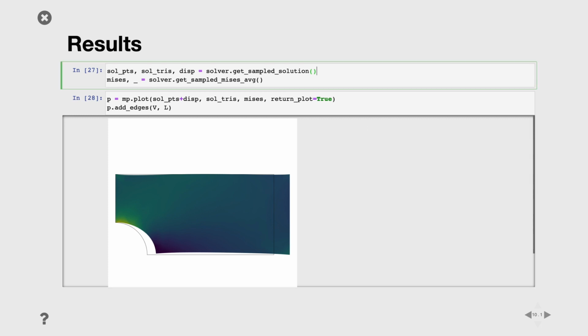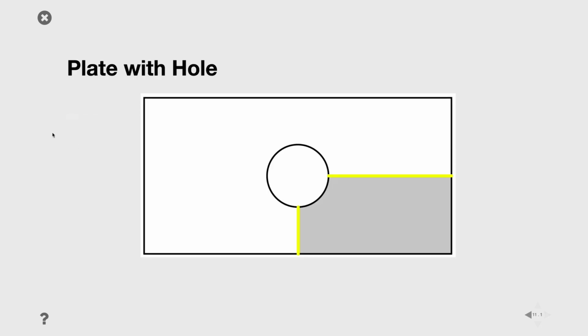If you ever did some finite element simulation, finite element testing, or opened any textbook, you may have recognized the mesh or the domain I'm using. So this mesh or domain is just a quarter of a classical domain, which is called the plate or plane with hole. So this is just a rectangular domain with a hole in the middle, and it became popular because it's a classical test example. And in the example here we have this plate with hole, and we just want to pull it, to apply some force left and right. And for efficiency and symmetry reasons, there is no need of solving the problem on the whole domain. We can just solve it on a quarter of the domain, which is this tiny piece here on the bottom.